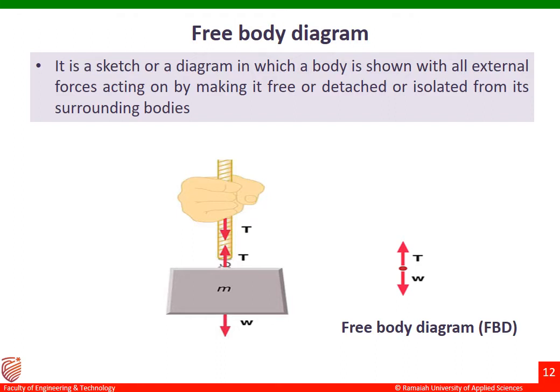The next topic is free body diagram. As I was telling in the previous slides, I was discussing the free body diagram of this person, the free body diagram of that block. So what do you mean by free body diagram? It is a sketch or a diagram in which a body is shown with all the external forces acting on it, by making it free or detached or isolated from its surrounding body. You can see the example here.